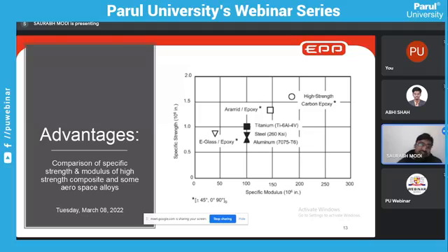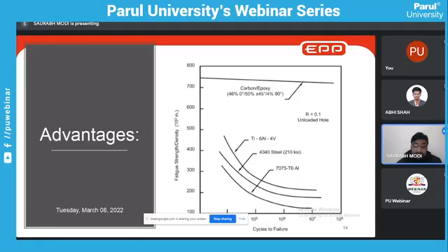So here it's just the comparison of specific strength and modulus. Again, fatigue you may have studied or you will study in machine design, where there is endurance limit and everything will come. So it is assumed that the world's 60 to 70% of components get failed due to fatigue. And in case of fatigue, the component fails below the yield limit only, because generally we mechanical people are familiar with ultimate strength, and we have a mentality that once the stress reaches ultimate, then it will fail, just because of our stress strain curve. So here in fatigue the case is different.